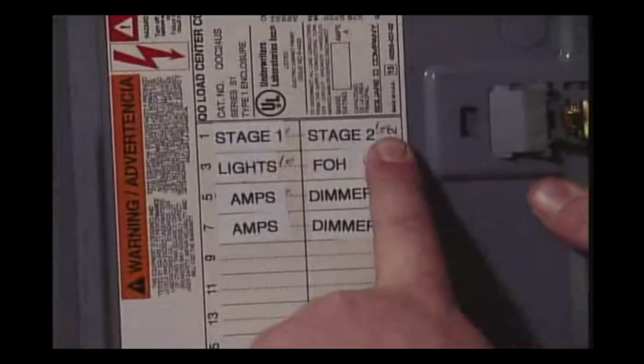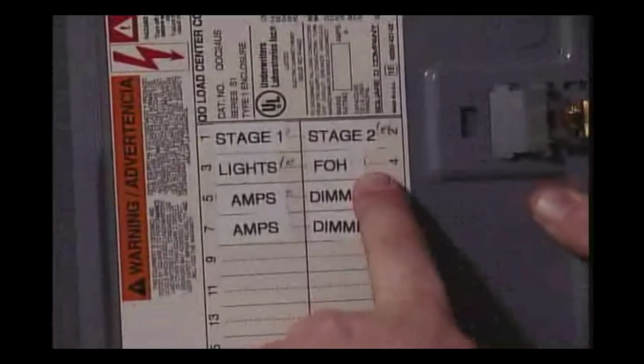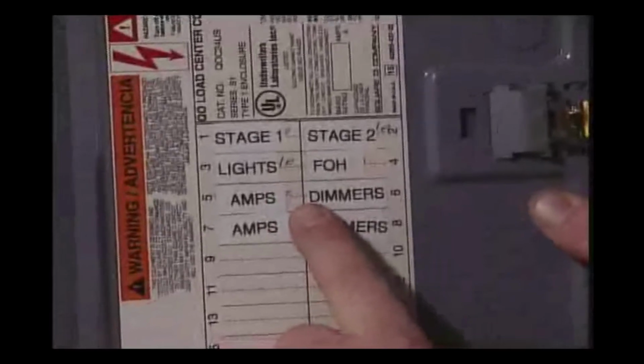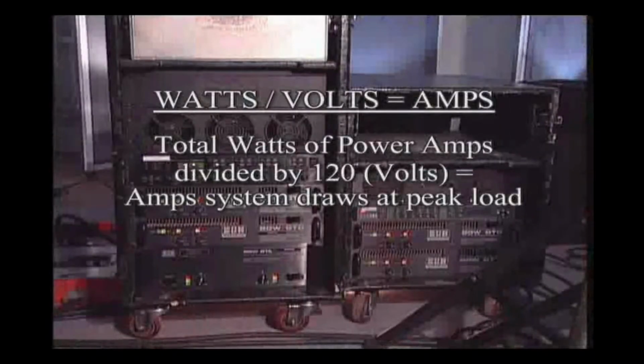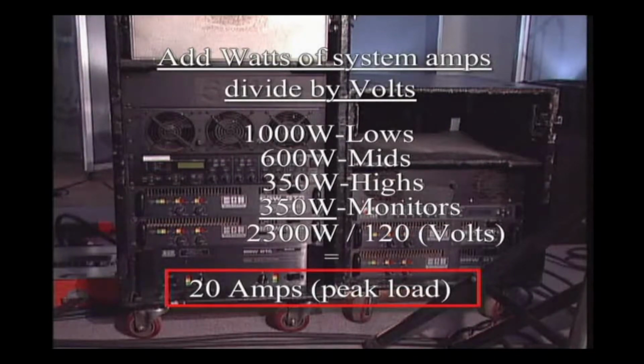Ideally, you want to have 1 or more 20-amp circuits just for the sound system. It's always worth trying to find this information out from the club manager or building electrician. Also, it pays to have an idea of what the power needs are for the system you're using. The formula for this is watts divided by volts equals amps. Add up the total watts of your power amps and divide by 120 for volts. The resulting figure is the amperage your system draws at peak load.